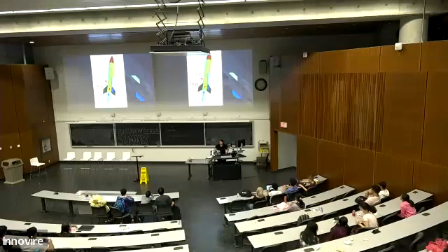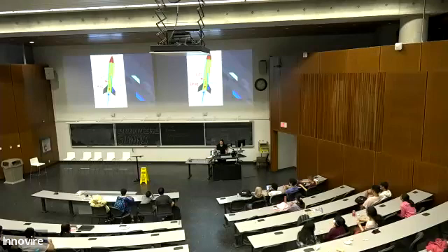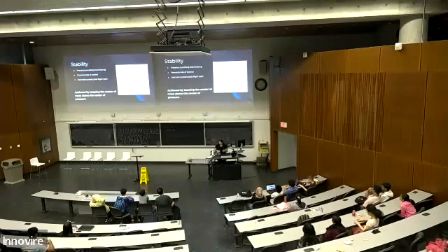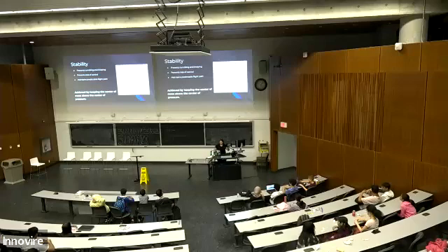Two important components of rockets are the center of mass and the center of pressure. The center of mass is basically the middle of it, where the middle of the mass is, and the center of pressure depends on the drag and the lift forces on the rocket. In terms of rocket stability, the center of gravity always has to be above the center of pressure. If it's not, then you'll get a rocket that tumbles.